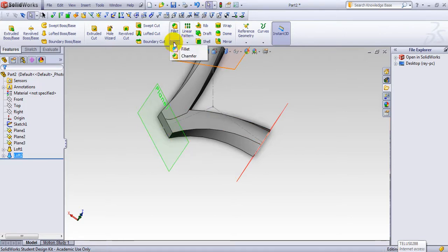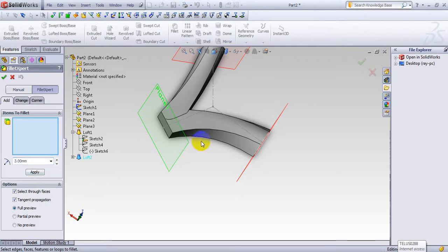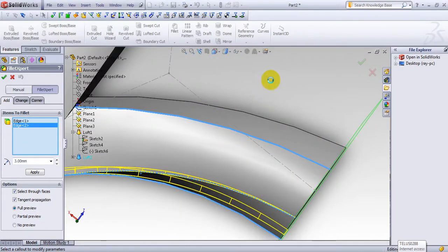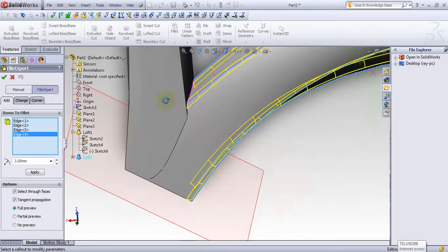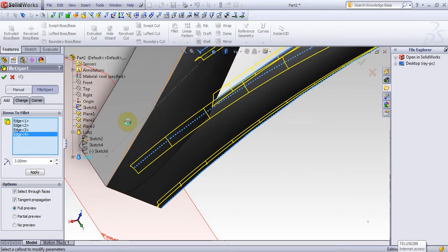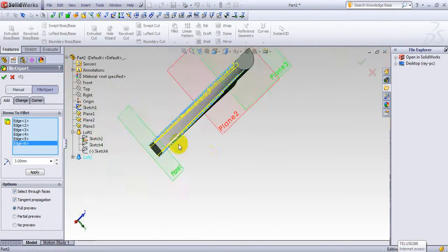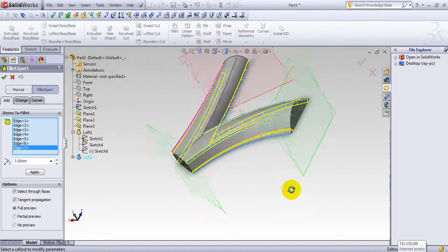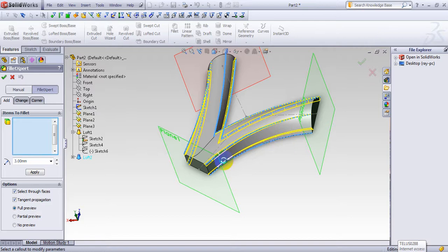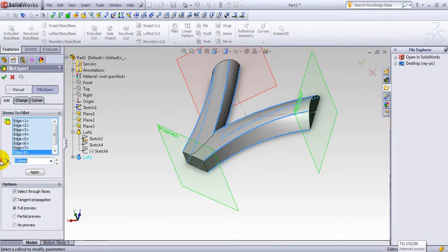Let's make a few fillets. So we go here to fillet, and I make it 3, and then you perhaps can do all of the angles here. Make a fillet, make it smoother. So here, one more, and one more. And here, and if 3 is too big, we can make it 2 later on. And here, and this one. Okay, and I reduce that to 2.